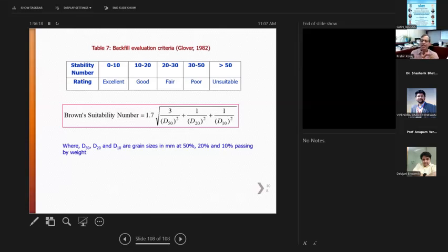So basically, whatever we explain here is just guidelines. With the peak particle velocity and other things, and the energy, you can readjust the weight, hammer, height of drop, and all these things. This will give you a guideline, and also what type of frequency you are using, which tells you which one is detrimental. So you need to check all these factors and see which one is best suited for a particular site condition.